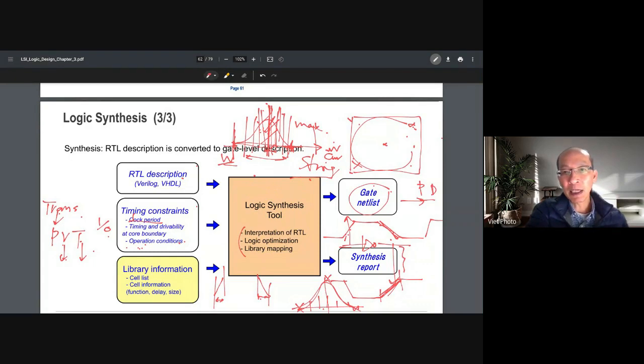Let's say the spec is 40 nanometer, which is supposed to be typical, but the transistors vary by, let's say, 10%. You have 42 here, and 38 here. So the variation is about 10%.